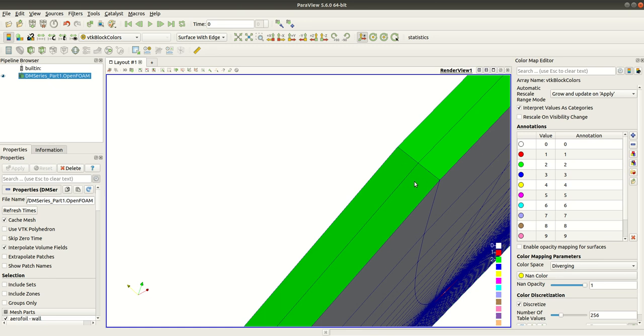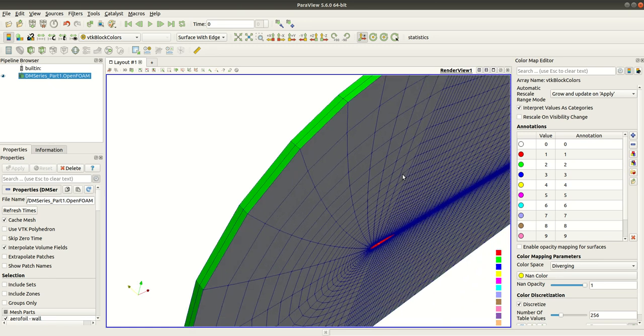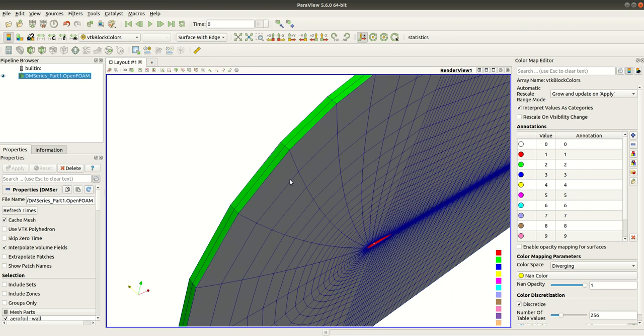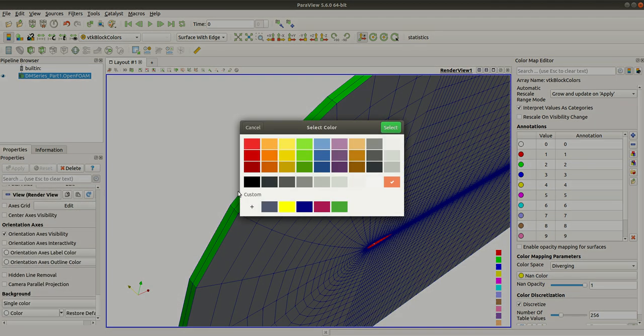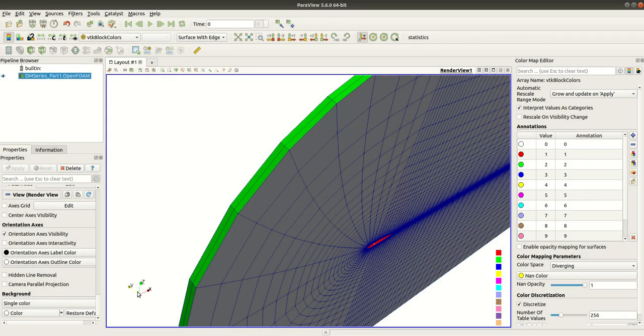This is not good. So I want to use extrudeMesh to extrude the 2D, the infinite direction face, the face normal to the infinite direction. I want to extrude this boundary along the infinite direction, which is y here, the y direction, which you can see here, and I want to have only one cell in this direction.